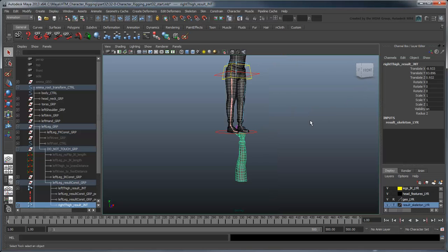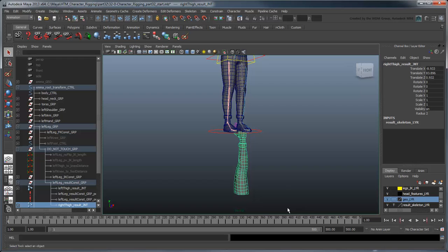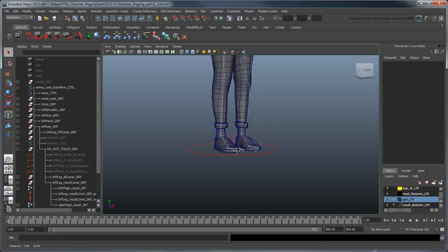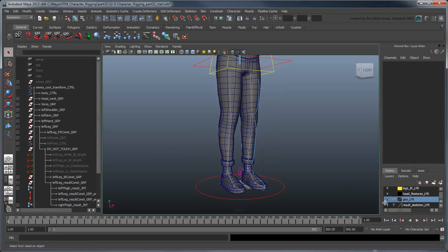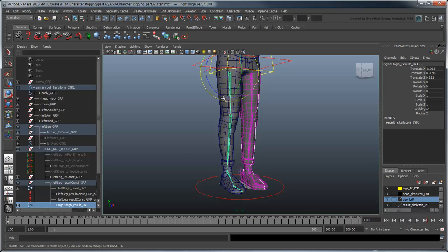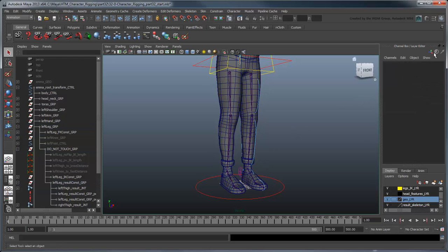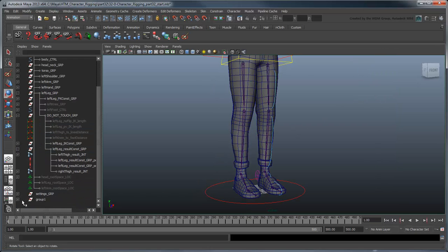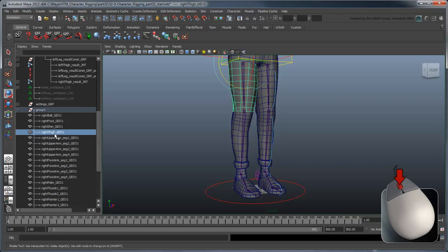However, because of the orientation of the leg versus the geometry, the results aren't quite right. Delete this extra geometry. The new joint orientations facilitate the mirrored rotations we want without inversing the scale. Now parent the mirrored leg geometry from before to the appropriate parts of the leg.